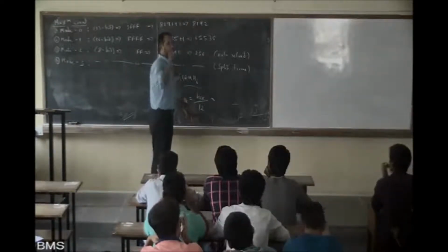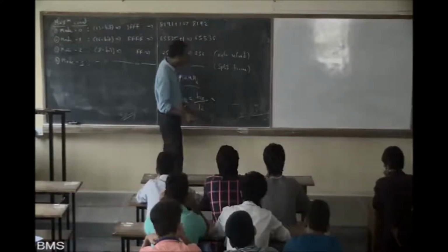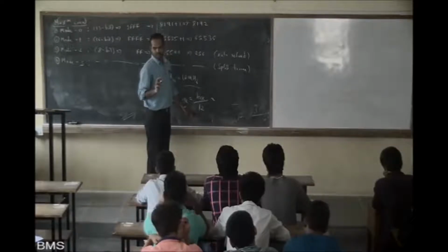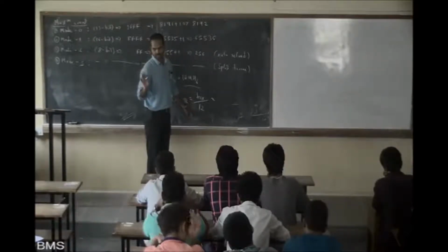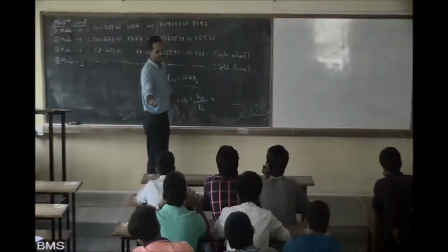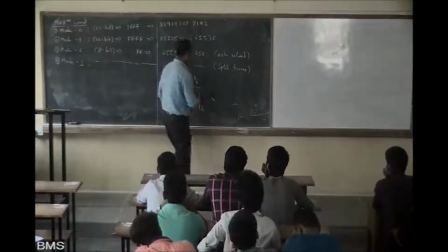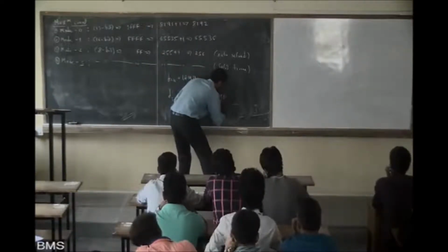Machine cycle will change for different 8051 controllers, but this 12 remains the same. So this is not the machine cycle 12. Is that clear? This 12 will give us 1 megahertz.